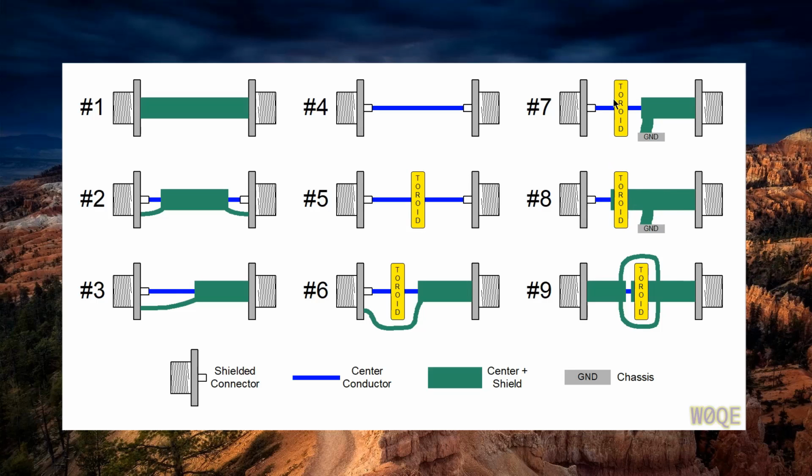if we want to measure capacitance from the center conductor to the toroid, we can measure it right here very obviously. Here, there is no capacitance from the center conductor to the toroid. It has been eliminated. What we see instead is capacitance from the center conductor to the shield, and then we see capacitance from the shield to the toroid, provided that this ground connection is very, very close to this and is a good ground connection.